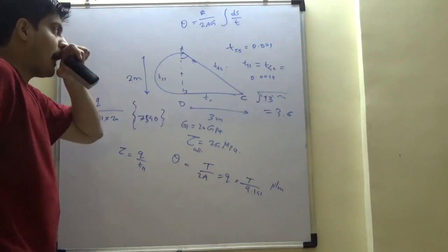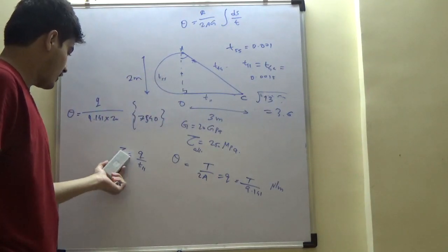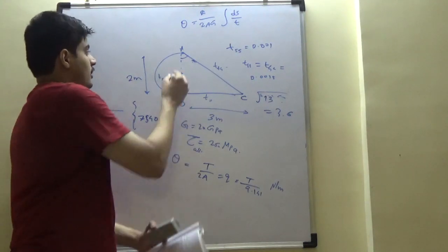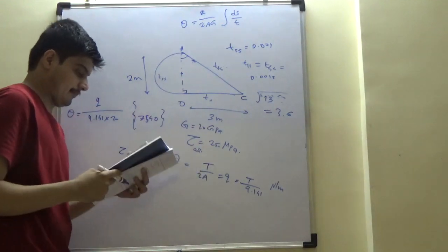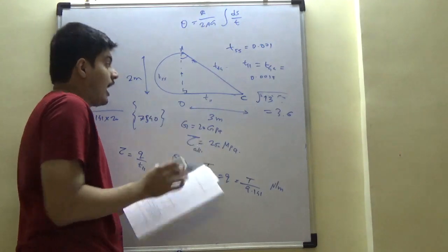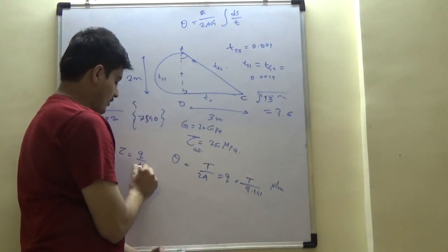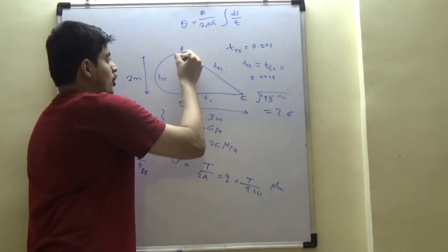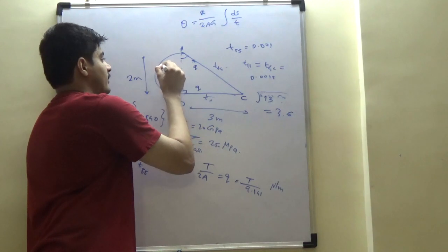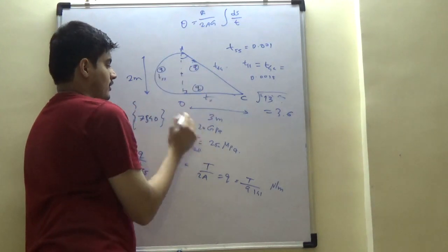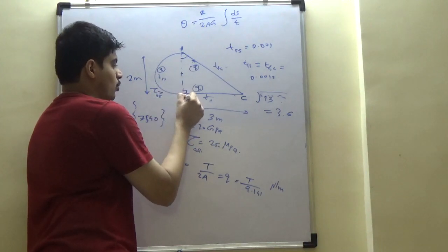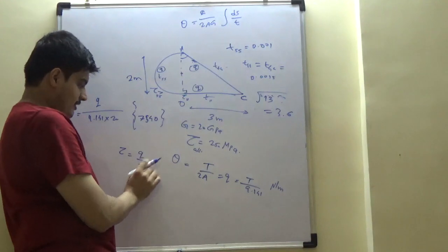The stress depends on thickness for a given shear flow. Here the shear stress is higher than the straight wall, correct? Which means I have to look at the least thick, because the same shear flow is everywhere, and the stress is going to be more where the wall is thinner. So tau 55 is more than tau 11 because of this relation.